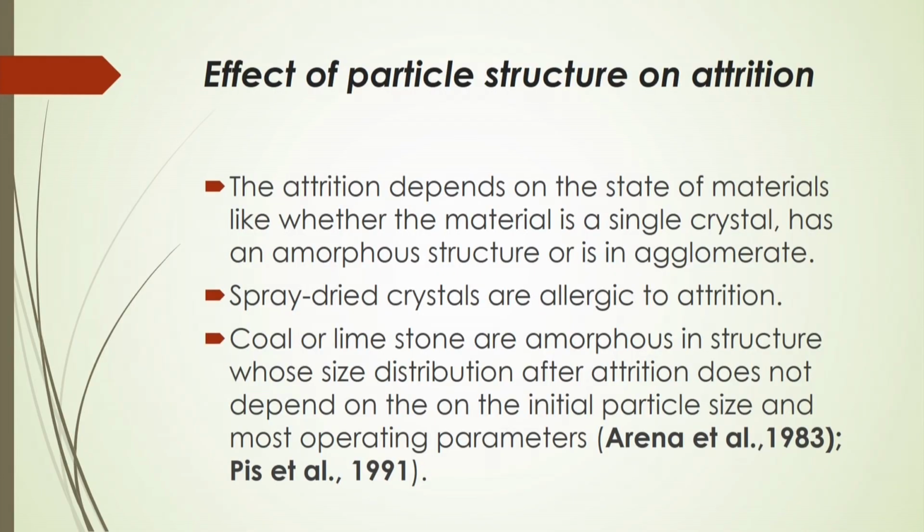And coal or limestone are amorphous in structure, and it is seen that the size distribution after attrition does not change significantly with the initial particle size, and also with most operating parameters. There will be no change to the amorphous structure of coal being attrited into smaller sizes.